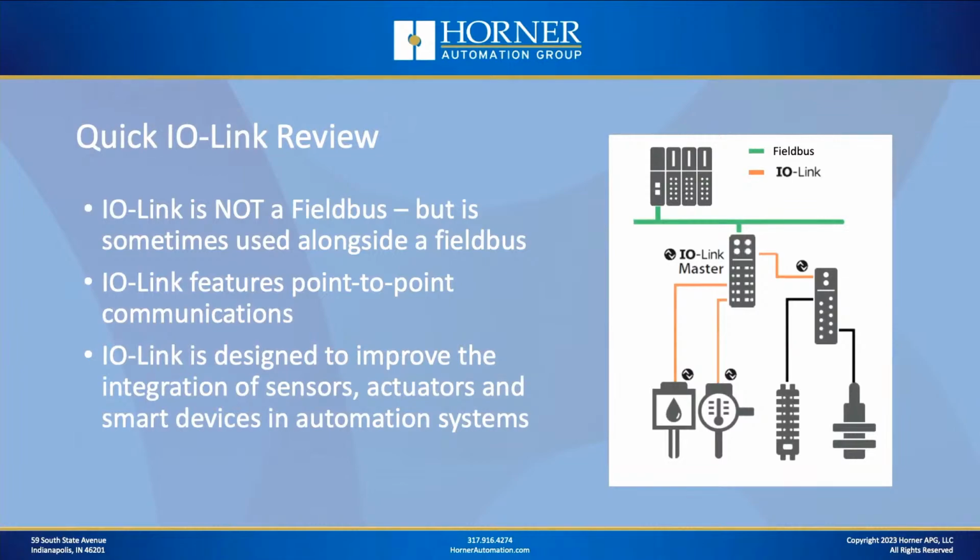All right, let's do a quick IO-Link review. First of all, IO-Link is not a Fieldbus. I know a lot of us kind of think of it that way, but it's not a Fieldbus. But it's often used alongside a Fieldbus. IO-Link differs from Fieldbuses in that it features point-to-point communications. Pretty much all Fieldbuses that aren't Ethernet-based are pretty much a multi-drop type architecture, if you will.